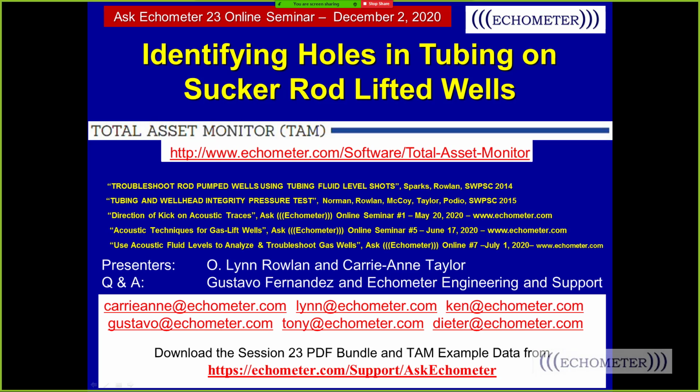And Russell went to a well that had a lot of gas interference, probably 60%, and it was really gassy. He let it pump for 2 or 3 or 4 hours until the tubing unloaded, and then it wouldn't pump anymore. We've got the data on that, which we've talked about in one of the previous presentations, and I think I even show the data. That data is available, and if you want, email me and I'll send it. We can review it, because it shows that the pump actually stopped pumping and they couldn't get it to pump anymore because the tubing unloaded.